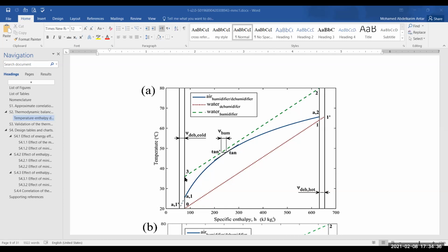Look at the differences between the enthalpies. At point 3 here, the value of the enthalpy difference at the exit is big. The enthalpy difference here is almost too large because this line has a smaller increase in the value or the trend. The slope is decreasing, which means that you may or may not have a line connecting between point 2 horizontally to point A2. So in the humidifier, where is the point of the enthalpy pinch, the minimum enthalpy pinch? It is this in the middle.